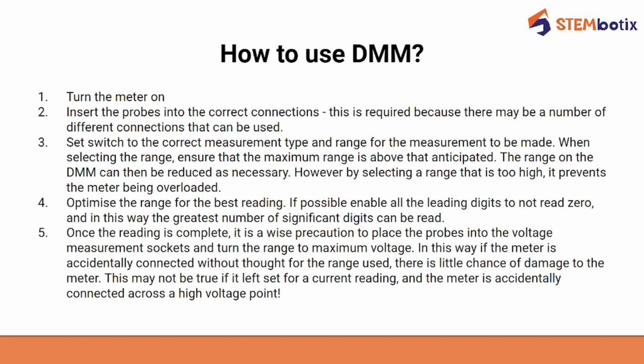Now, the fourth step is to optimize the range for the best reading. If possible, enable all the leading digits to not read zero, and in this way the greatest number of significant digits can be read.